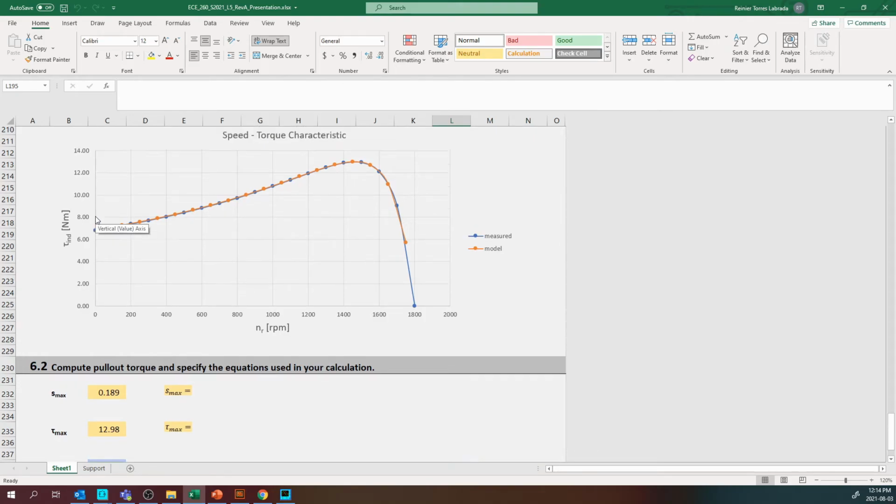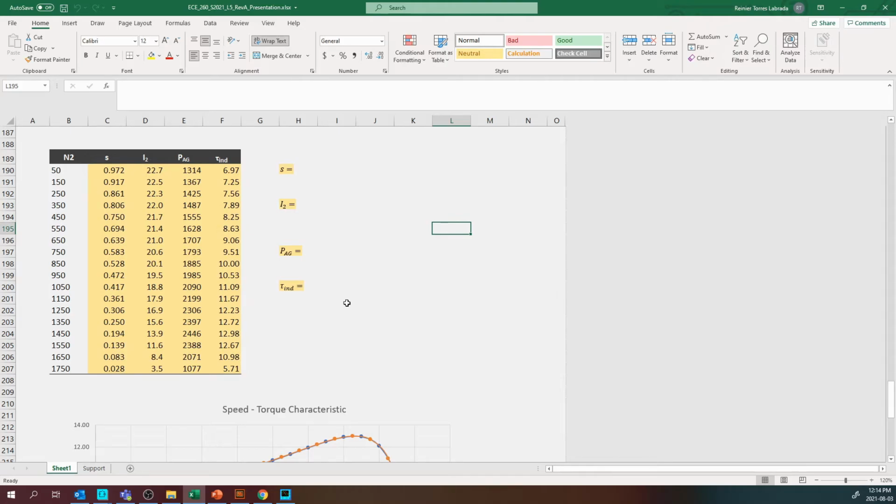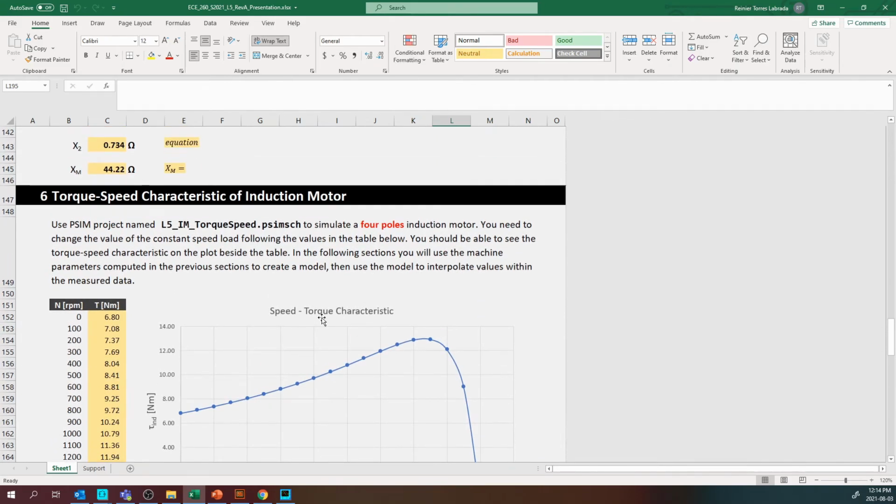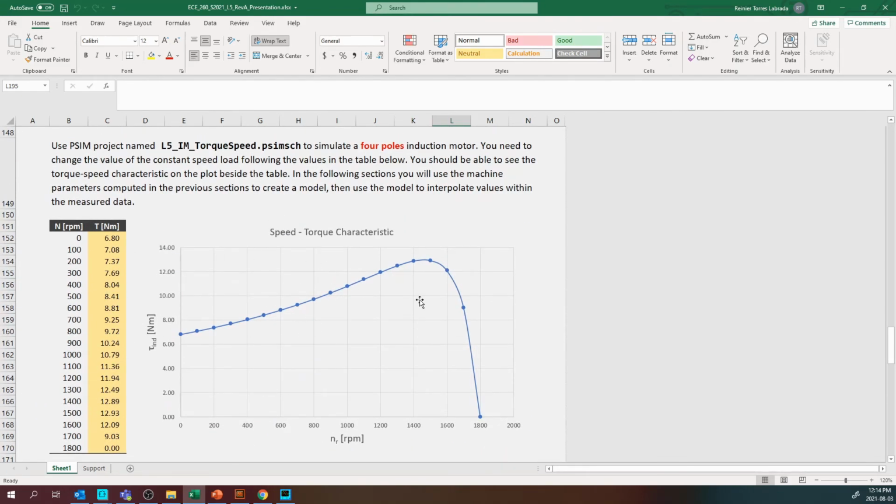And the reason why it's so cool is because it's really easy. It's really easy to run the DC test, the blocked rotor test, and the no-load test compared to trying to do this characteristic curve. And why so? Well, it's very difficult to find a load you can spin very well at precise speeds, and that can go all over this range from zero, like blocking the motor, until the maximum.